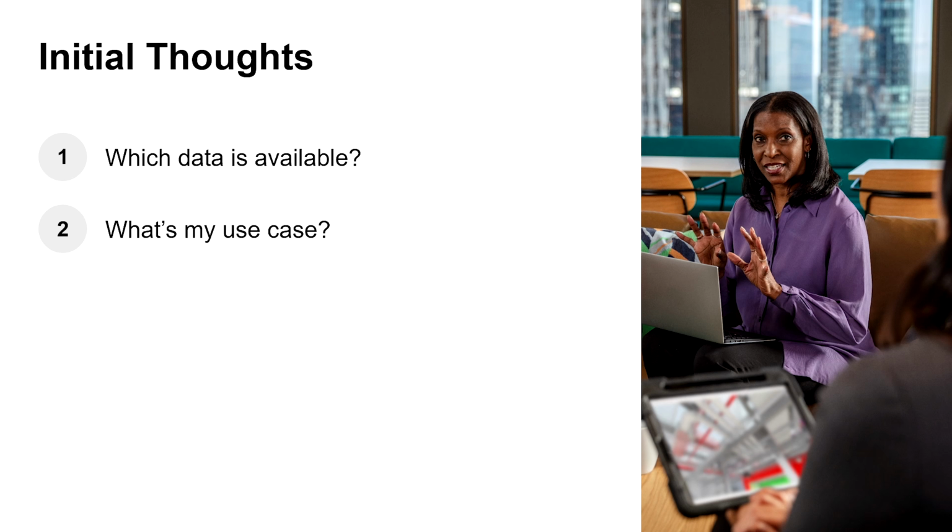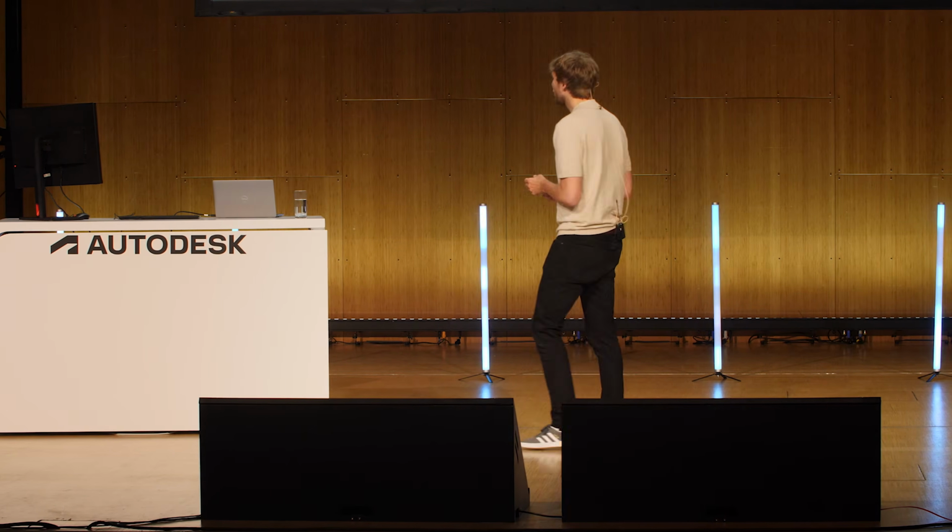For example, if I just want to work on the roof height of the car, just a bit higher, a bit lower, then it's easy to get away with, let's say, 5 or 10 data points. I train an easy model, a super small network, and I can interpolate between all those heights. If I have more sophisticated changes, like on a full production car, even a Formula One car, then obviously I need more data to tweak small areas of the car and have more refined changes.